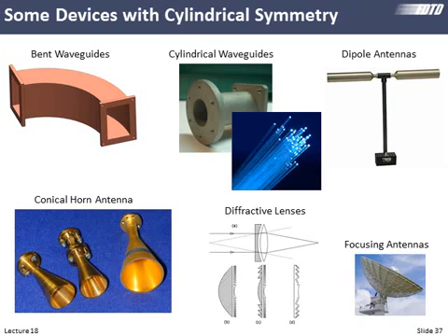There's a whole lot of stuff that have cylindrical symmetry, and we can buy ourselves a lot of efficiency going to cylindrical coordinates. There's even times where if we had a Cartesian grid, we would need a three-dimensional model, whereas sometimes we can model three-dimensional things in two dimensions if they have cylindrical symmetry. So it would always be good practice to do that if we can.